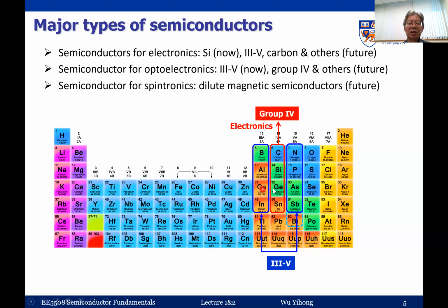In fact, the first LED and laser diode was made from gallium arsenide, right? But for gallium arsenide, the band gap is quite small, so that's the reason why, for example, if you make an LED or laser diode using gallium arsenide, the color you will see is basically in the near infrared, right? So in order to have visible light emission from semiconductors, you have to use other types of semiconductors. At that time, people looked at gallium phosphide, for example. This will give you green to yellow light, right? And then the red light.